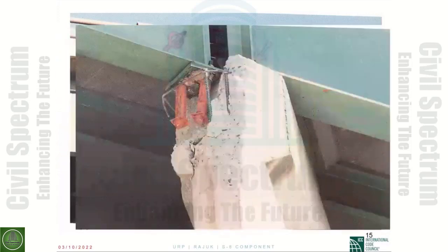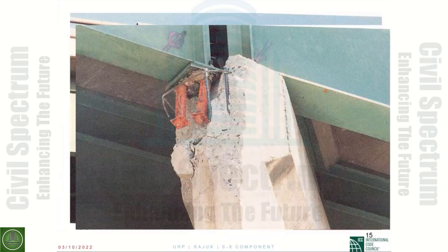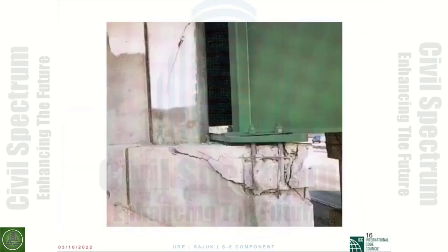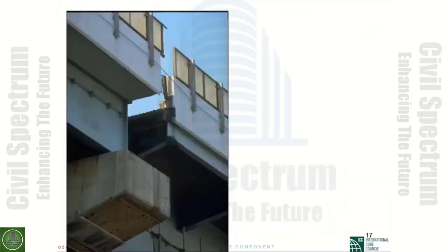If the earthquake had been a little bit bigger, that would cause the unseating of the plate girder. This is a close-up, and that will show you the lack of reinforcement details at the anchor rods. This is here at the abutment. It's the same thing. Same thing for a steel plate girder bridge, as you see the differential movement between the superstructure and the bent cap.